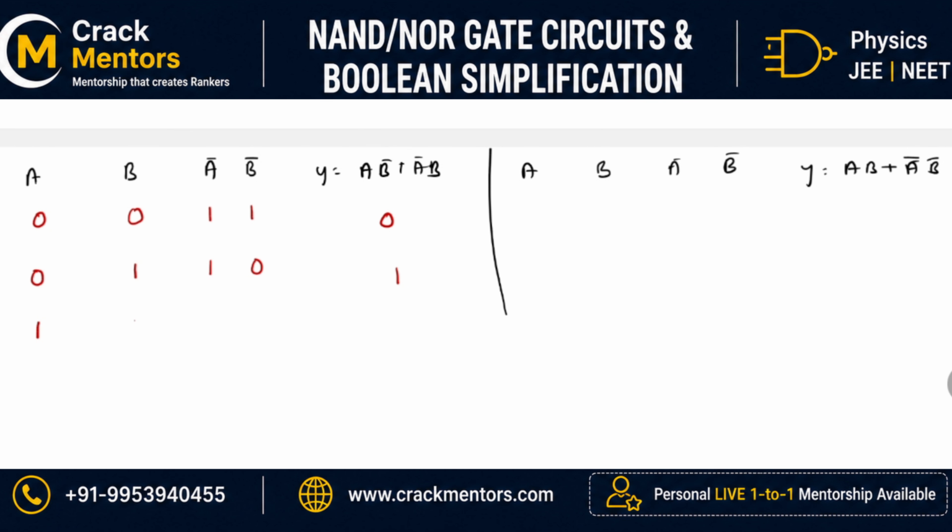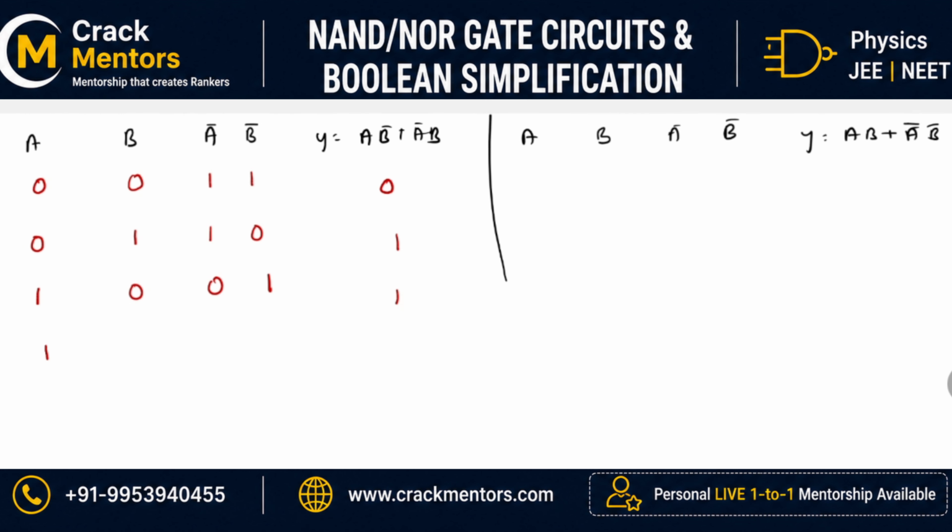What about the third one? If this is 1, this is 0, this is 0, this is 1. I will be writing that this is equal to 1 into 1 plus 0 into 0. What does that give? 1 plus 0, that is again 1. And what about the fourth condition? If both of them are 1, so both of these are 0. This is 1 into 0 plus 0 into 1. This gives me a value of 0 plus 0 again, that is equal to 0. Is that clear? Okay, so this is the truth table for the XOR gate.